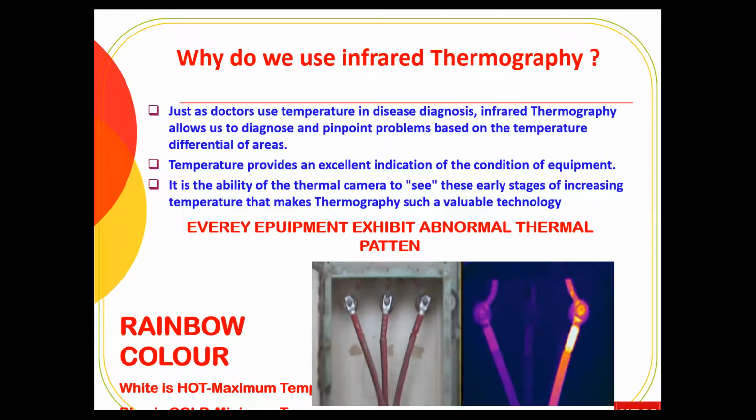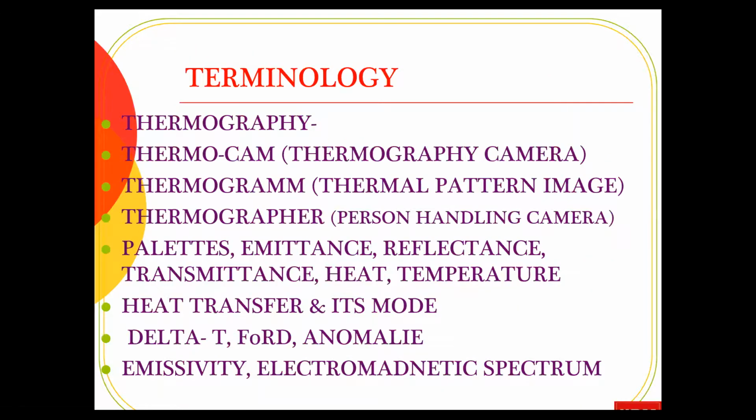But in the thermography camera, the record is a photograph or picture, a thermogram. So out of the three phases R, Y, B, in the B phase we are seeing different colors, and the total picture consists of different colors. Blue regions are cold, and white is hot, and red and white are very hot. So in this phase there is a problem, maybe a joint problem, joint looseness, maybe corroded, maybe pitted, maybe a contaminated substance. So okay. Before entering into the thermography world, let me tell you what the science of infrared image displaying in the thermography camera is. Through the help of hotspots we can judge so many faults.